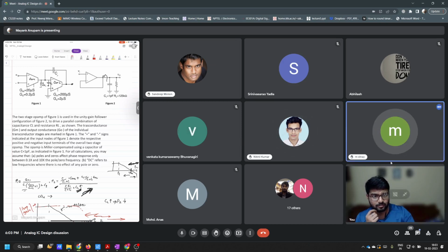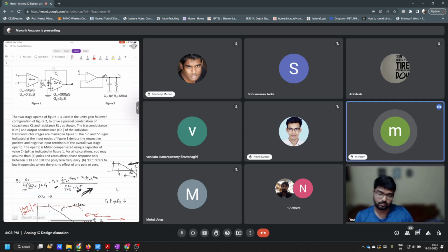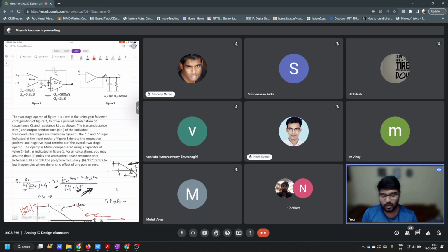Sir, one doubt, sir. Sir, calculating the R_out, you have to open circuit the V_i, sir, the input voltage. No, you are not open circuiting. You have to short circuit. Yeah, short circuit, sir. Then it will be only resistance, that is, g_o1 and g_o2 in series, no, sir. No, you also have to apply a test voltage here, V_T, and then you have to see what is the current that will flow.